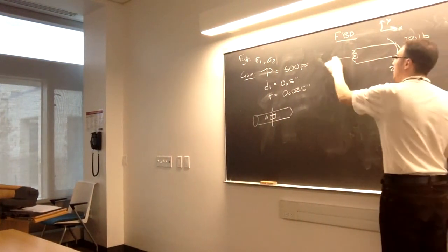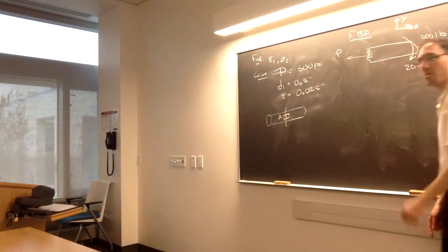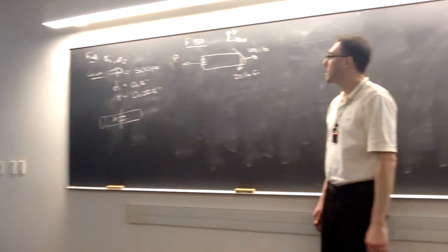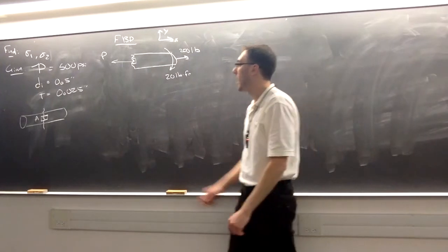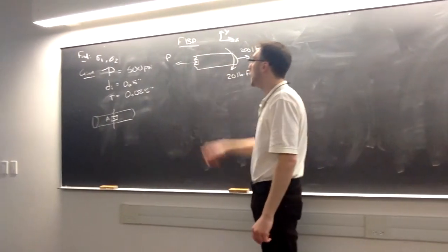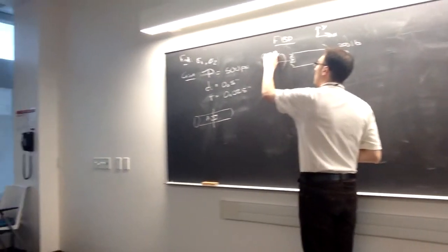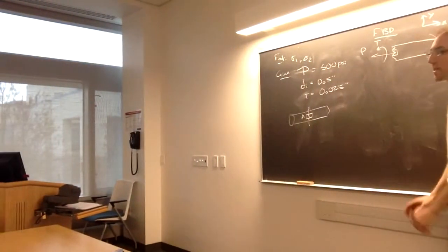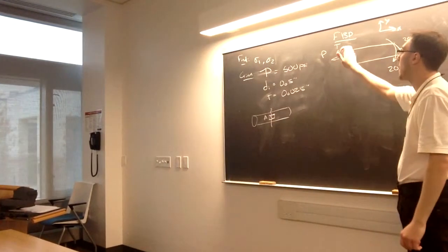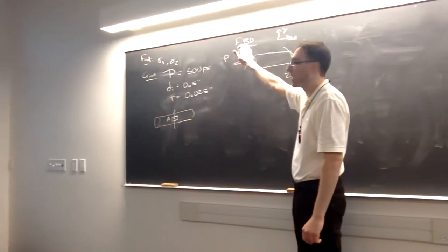Internally, I'm going to have this internal normal force, regular P, outward from the normal, outward from the cut surface. And then I'm going to assume that around that direction, I'm going to have my internal torque T. Right, so that's positive around the vector P.